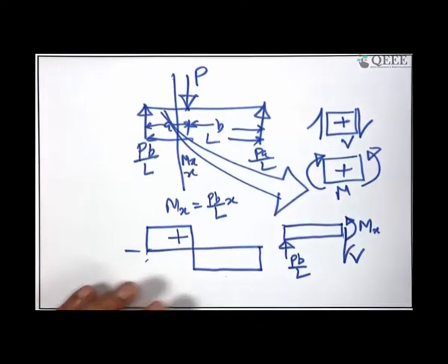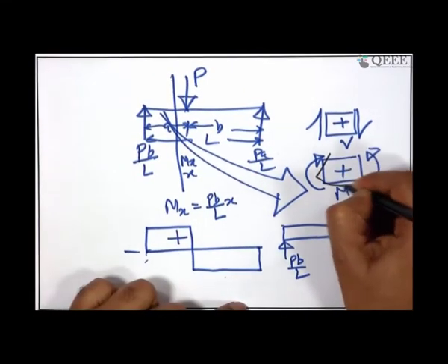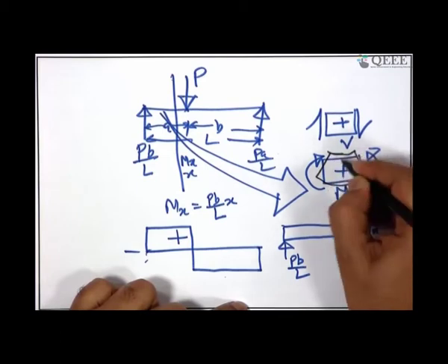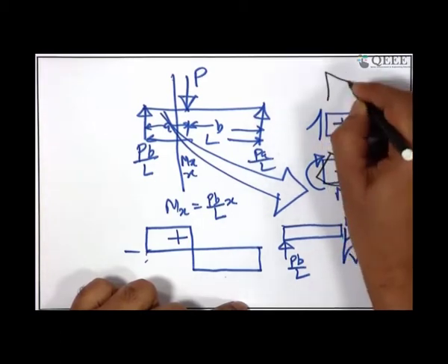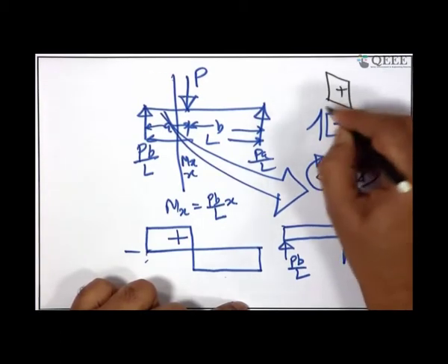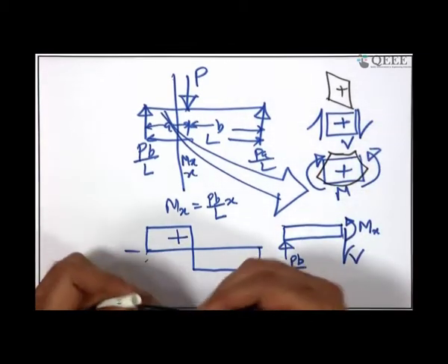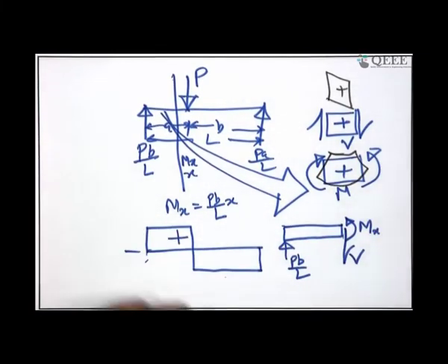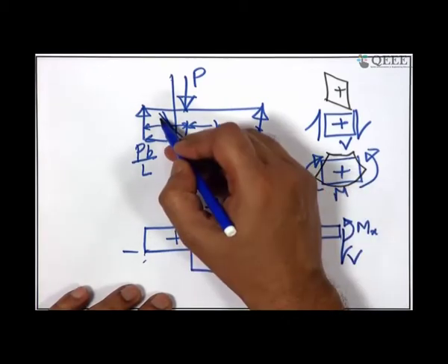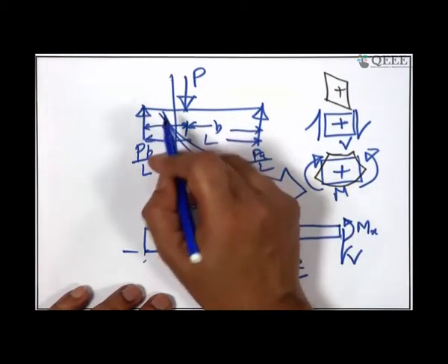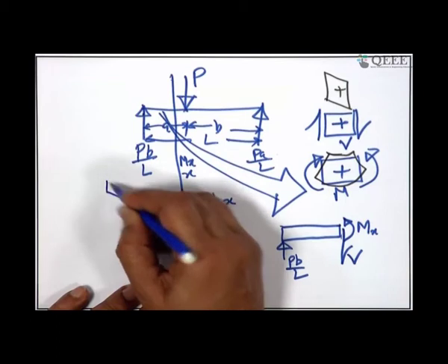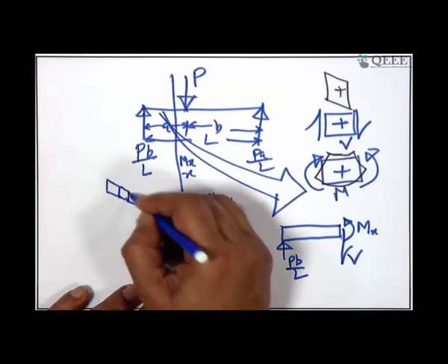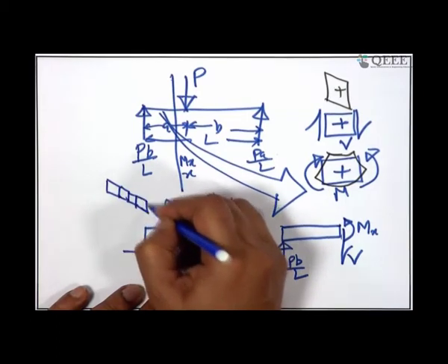So, I should have another color. It tries to bend it like this when it is bent, and this tries to distort it like this when it is left up, right down shear, and this if I take it positive. So, if I take it positive, then my shear force, in the absence of bending moment, will try to bend the beam like this, in a rhombic way.